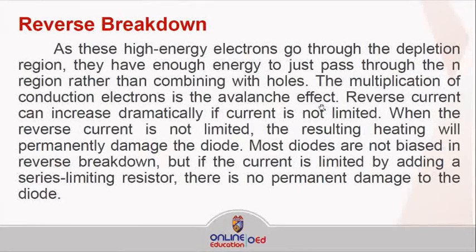Then, the reverse current can increase dramatically if current is not limited. Okay, pwede ring tumaas yung reverse current, increase dramatically kung hindi nalilimit yung current, or wala kang masyadong ginamit na resistor limit or R limit. If the reverse current is not limited, the resulting heating will permanently damage the diode.